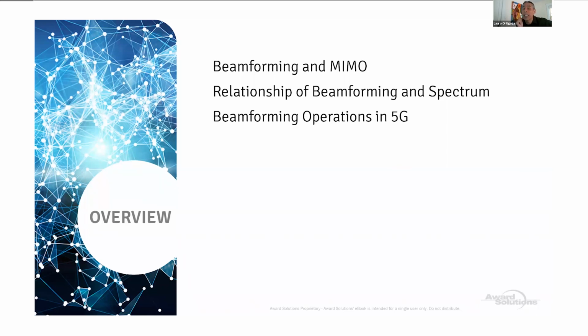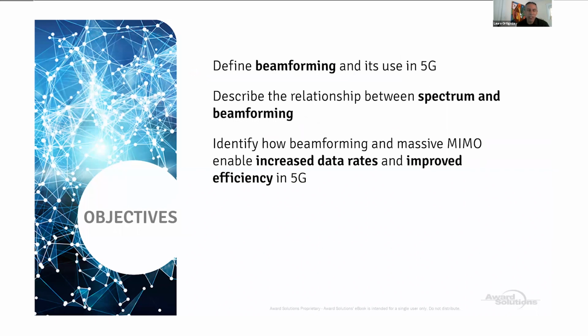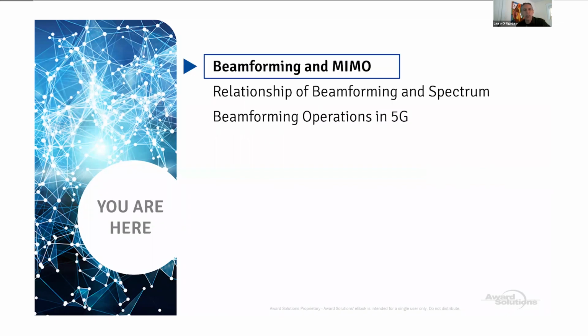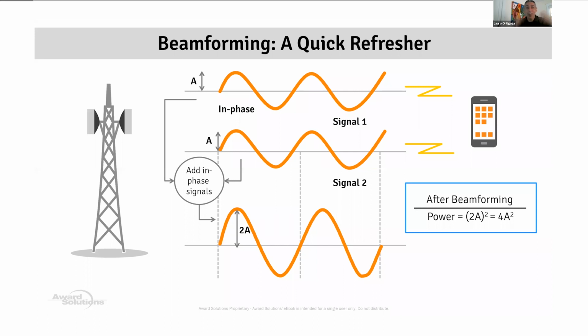So beamforming, amigos, is nothing else than sending or radiating energy in a given direction so that, for example, if we have two antenna elements, by modifying the amplitude and the phase that we inject to the two antenna elements, we can send this given signal in a given direction. So if we want to create a given beam in this direction, we're going to modify the amplitude and the phase of my symbols such that in this direction where my subscriber is, there you go.